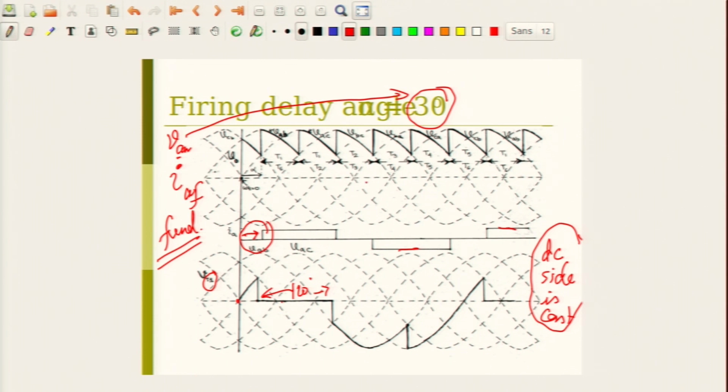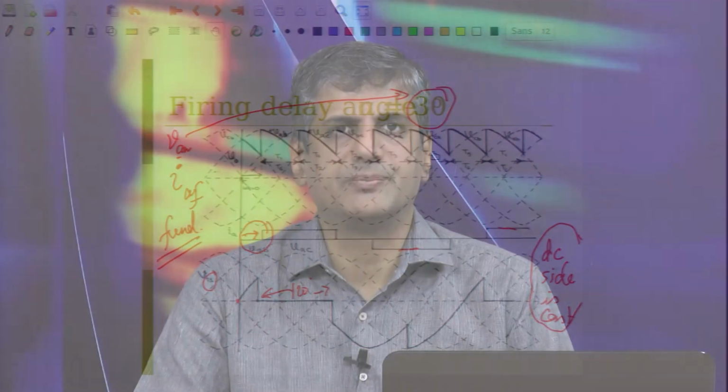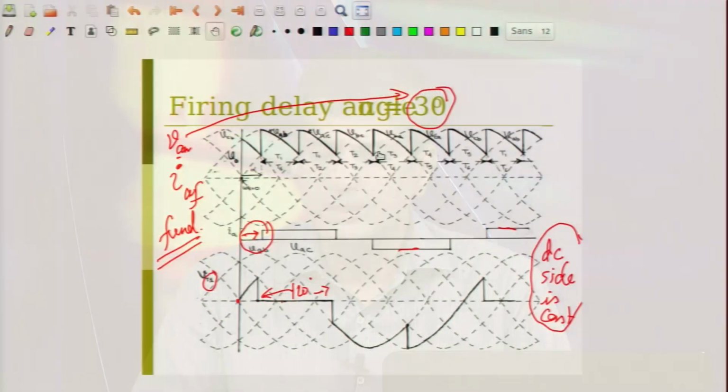So, even though the voltage which is applied to the inductor has got DC and a ripple, the ripple voltage does not cause a ripple in the current because the inductance is extremely large. Because the inductance is extremely large, it filters out or attenuates the high frequencies. So, what you find is the current will not have much of a ripple. The current is dictated mainly by the R of the circuit and the average value of this waveform.